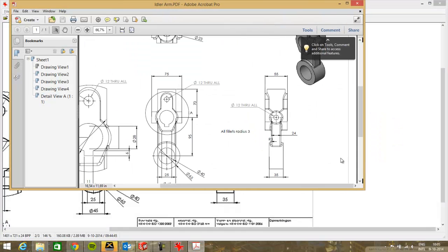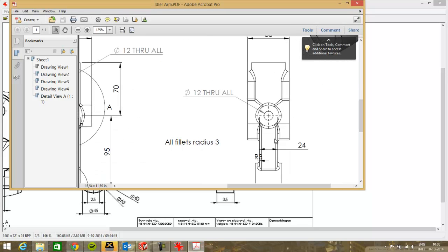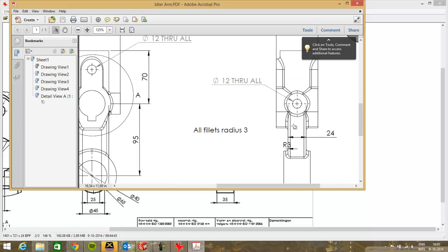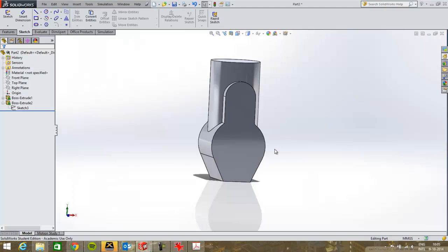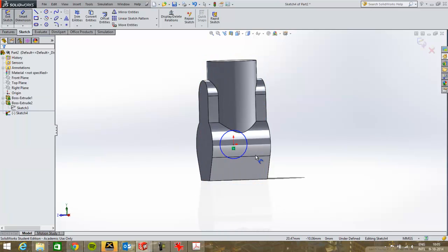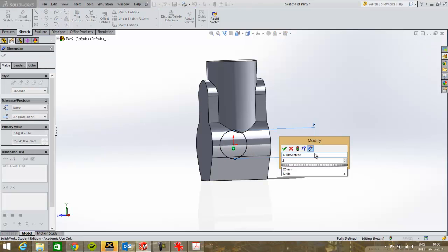Yeah. So I want to enter this circle right now, and the radius of that, I don't know if it's on the drawing. Let me see, otherwise I'll just assume a value to get close to the final result. It's just over 24, so I'll assume 28 over here. So I'll draw on the right plane a circle, and again, if your origin is in the right place, it's really easy. So I assume 28.